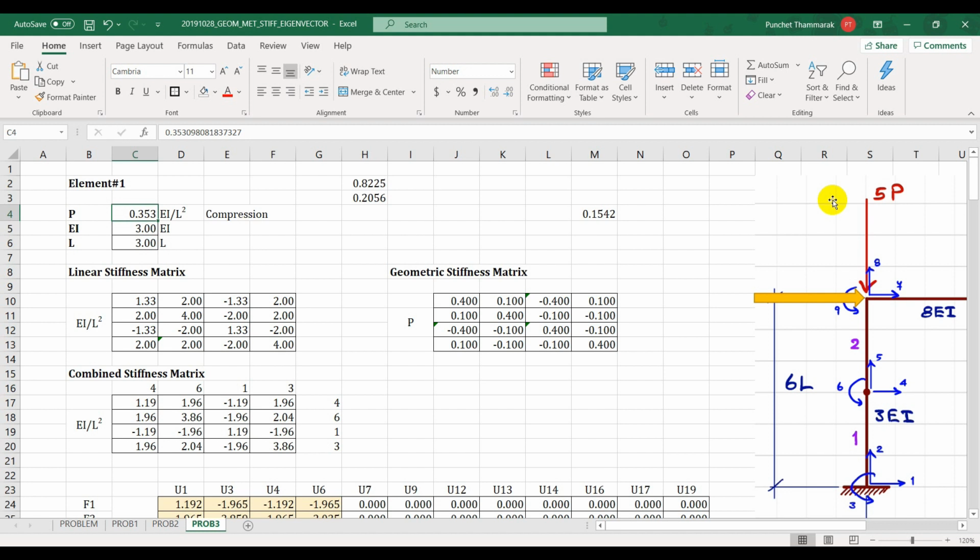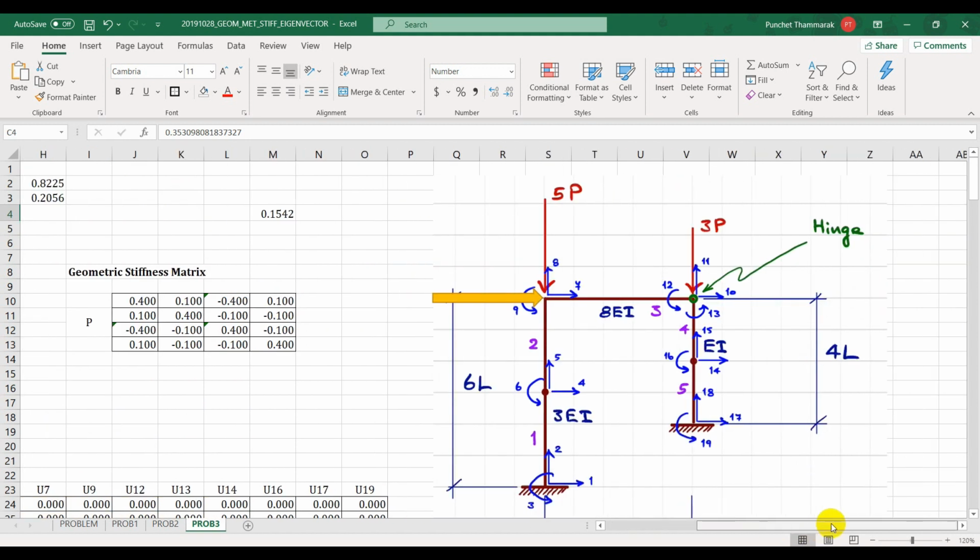If you keep running the analysis, you might be able to get more and more displacement, more and more load. But the load will approach one value, which is controlled by the Eigen buckling load. So let's try this one together.